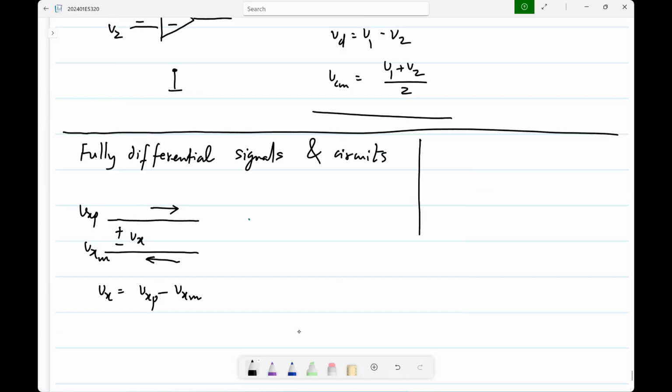So this is in contrast to when we say single-ended. What does it mean? You have a number of voltages, I'll show voltages, but the same applies for currents also. Voltage is always a difference, but we specify only one node. What we mean is that basically the voltage signal is the difference between that node and the common reference node. Whereas when you have fully differential signaling, we dedicate two wires for each signal. Two nodes, and your signal will be measured as the difference between them.